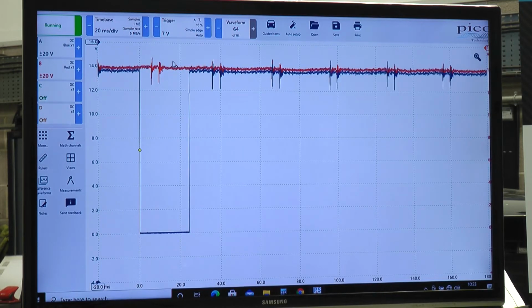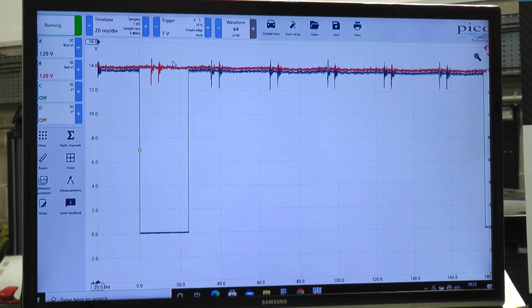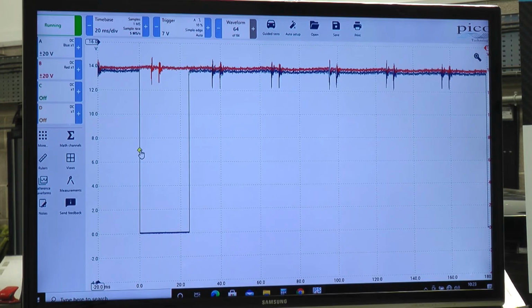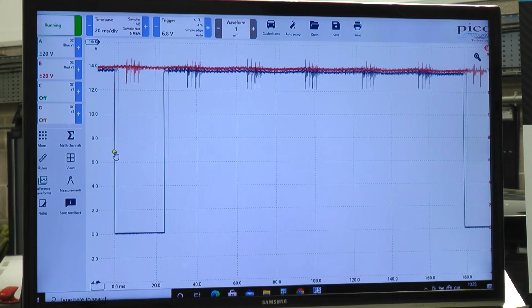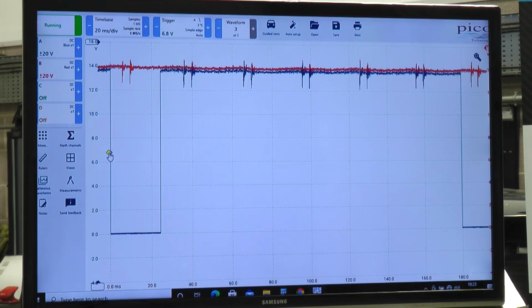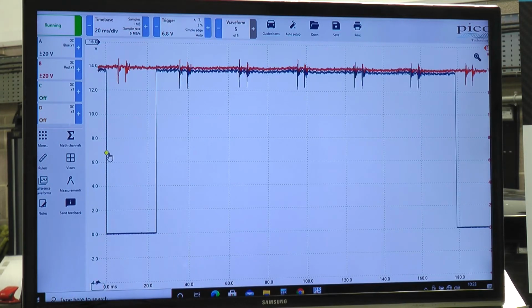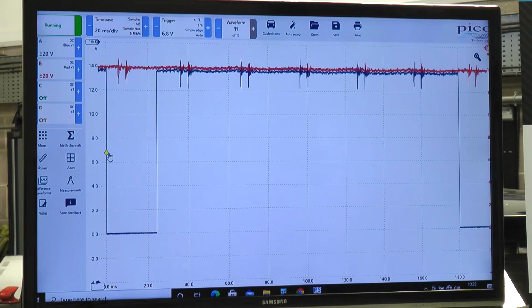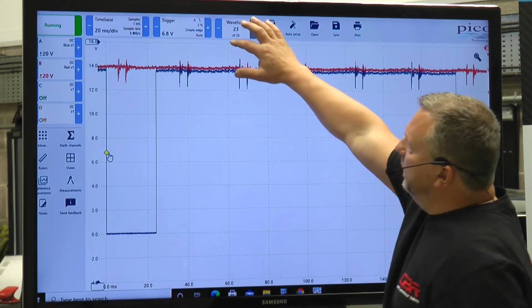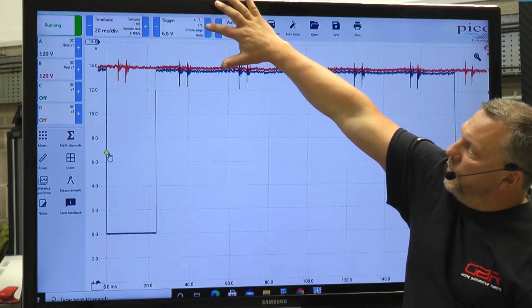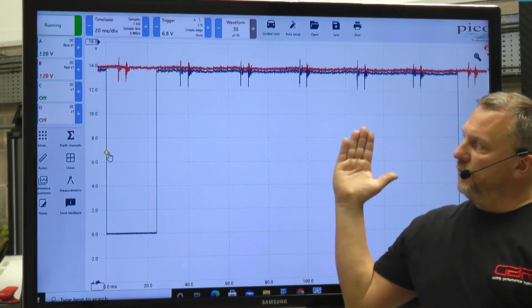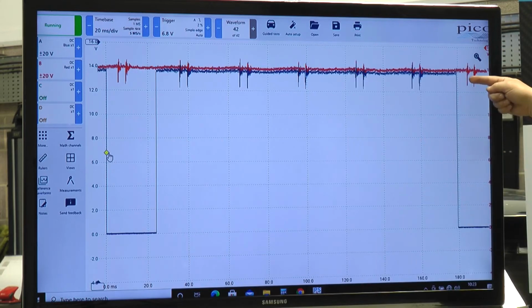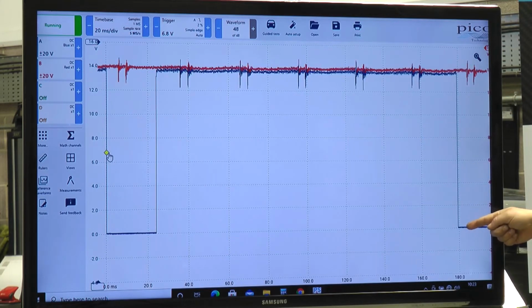So unfortunately, how we've selected it means that the end of our sample isn't quite on the screen. In this case, you can grab the trigger manually and move it. Notice, we've gone down to 2%. Moving the image across that way so we can now capture the start of the next event.